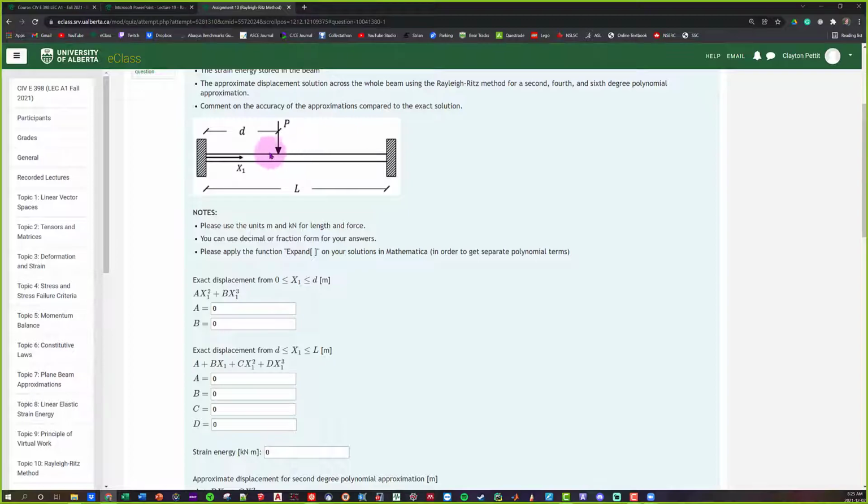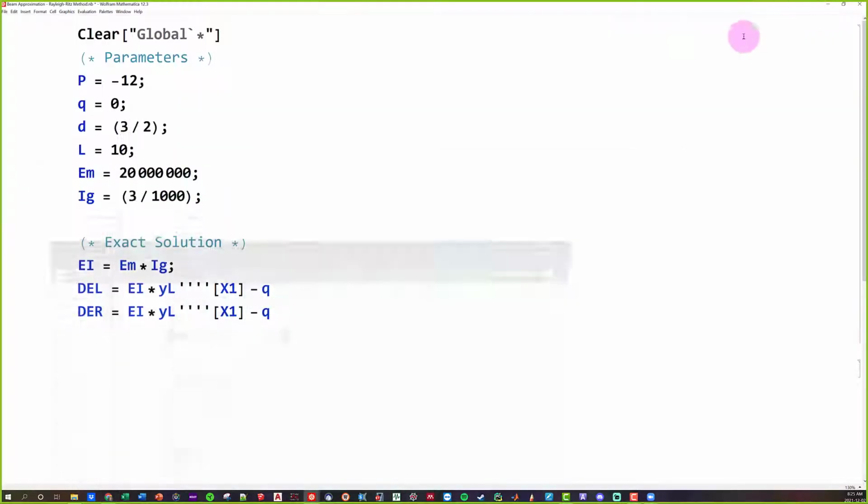But one of the things that you might see is, let's say that this part right here was made of concrete and this part right here is made of steel. We know that the stiffness of steel and concrete are going to be different from each other. So in cases like that, it would be useful to know how stiffness basically works. But back to this equation, EI stays the same. Displacement function for the left, well, in this case we want a displacement function for the right. So that's all the modifications. Q is just going to be the same. So we've now defined our two differential equations.